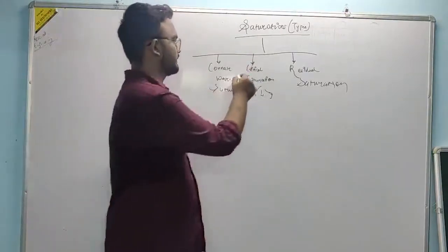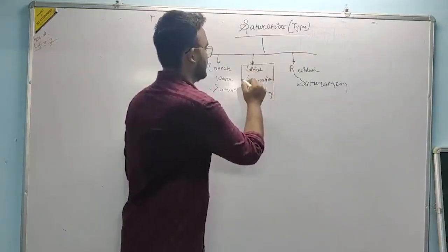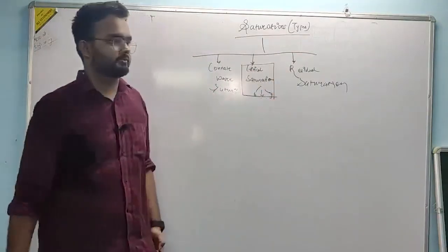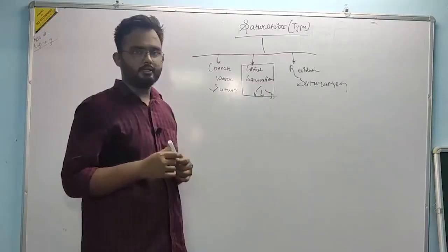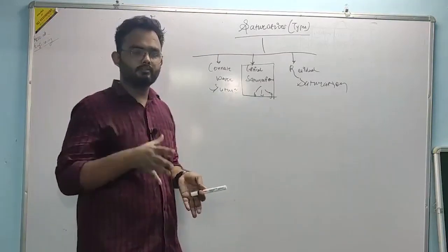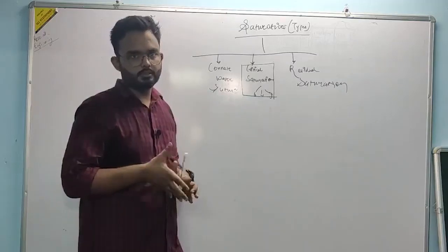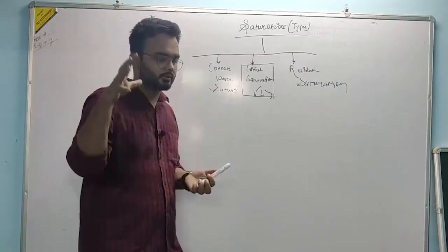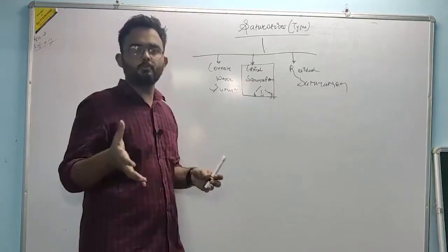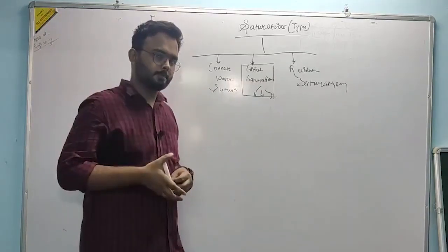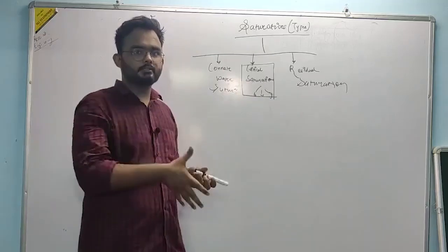Now this is important, critical saturation. I'll try to give you a perspective. For example, you have oil in the reservoir. Oil can have gases dissolved in it, but that requires a higher pressure. So let's say the reservoir pressure is higher than bubble point pressure initially, and gases are dissolved in oil.